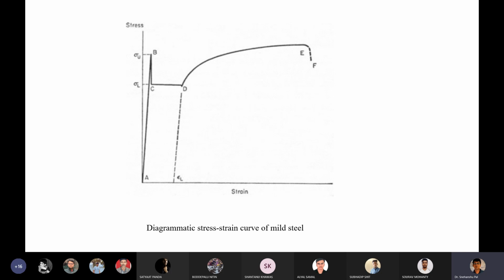In this stress strain curve, we can observe that it is not at all smooth, and there are certain irregularities, and you can see the negative slopes occurring at or near the initial yielding of the curve. The actual shape of the stress strain curve depends to some extent on the type and characteristics of the tensile testing machine used.